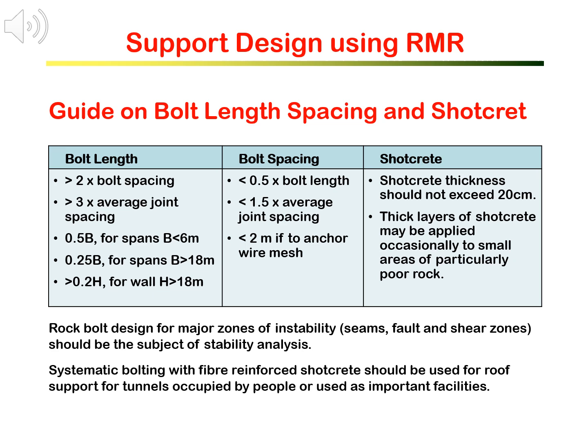The RMR rock support guide indicates the thickness of shotcrete. However, for shotcrete, particularly fiber-reinforced shotcrete, the thickness should not exceed 20 centimeters. Thick layers of shotcrete may be applied occasionally to a small area of particularly poor rock.